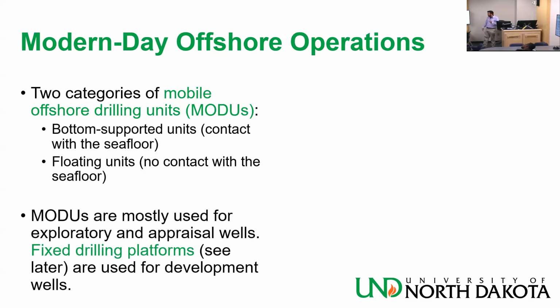Exploratory is a wildcat well. You are brand new in the area. It's the first well that you drill there. Then you have the appraisal wells, which is, there is oil there. You are trying to find the limits of the reservoir, look at how the reservoir properties vary throughout the reservoir, the field. And the development wells is like you made your plan for those wells and you are drilling them as part of, we're going to inject water here, produce oil there, blah, blah, blah. They are very well designed wells for your project.